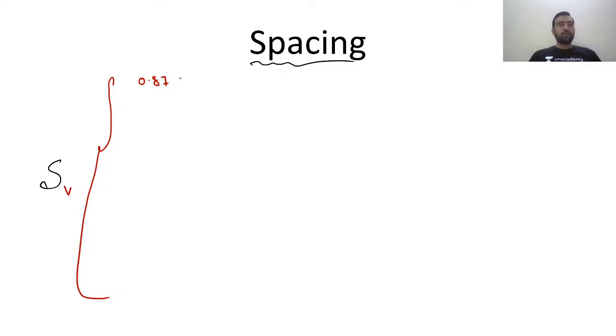Yes, it is 0.87 fy Asv d1 divided by Tu over b1 plus Vu, only Vu, not equivalent, over 2.5. So any comment, any doubt? So it is first.